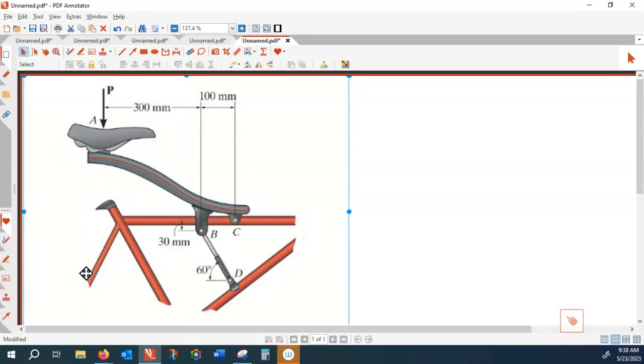So that way, I know at B the direction of the force, but the magnitude I don't. So one magnitude at B, two unknowns at C. The free body diagram for the beam only has three unknowns, not four unknowns. All right? Do you want me to explain again? Is that clear?